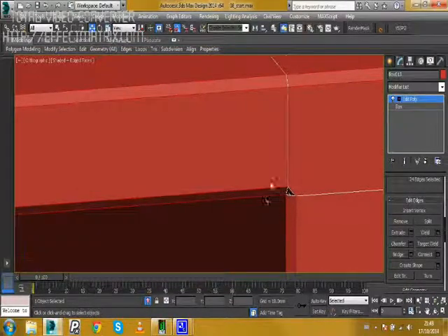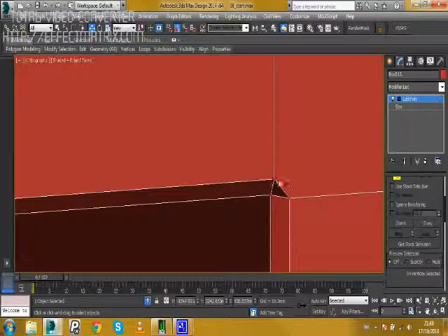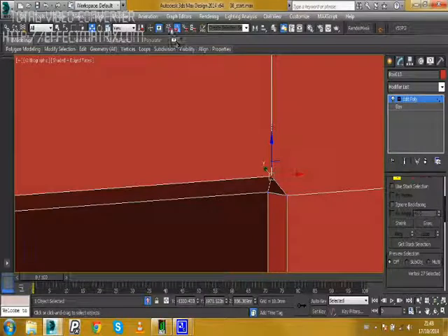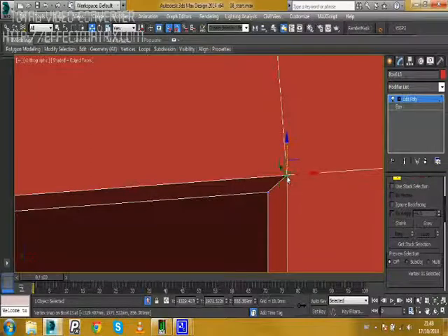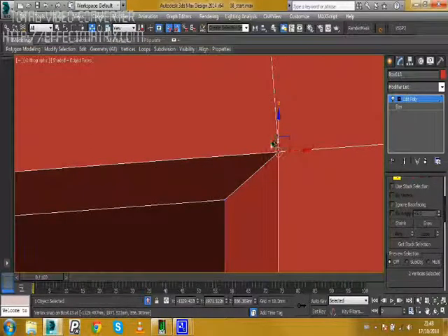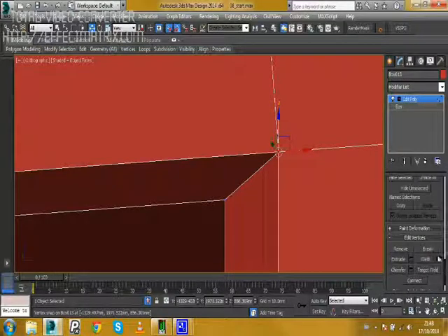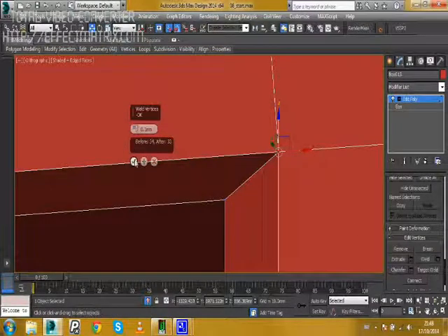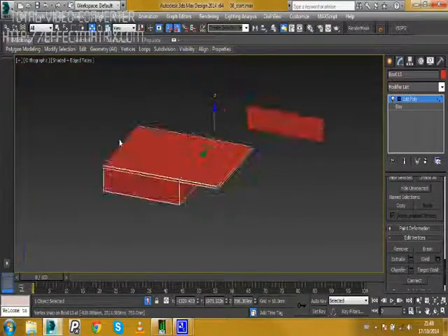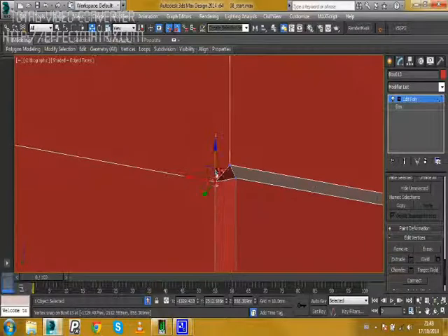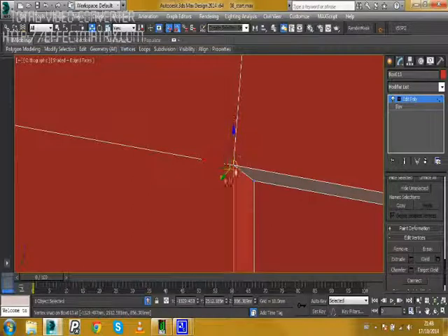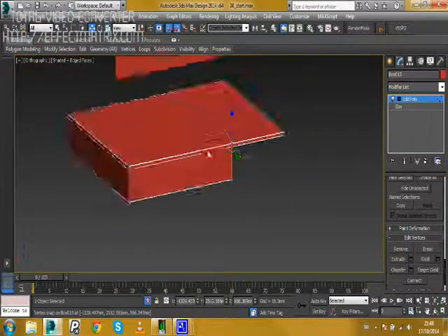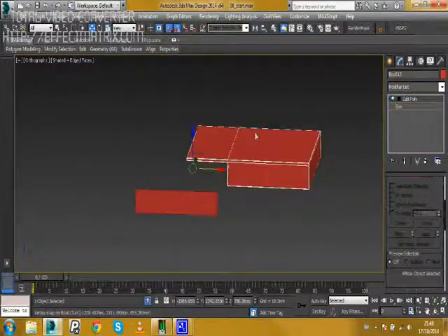You can see we've got some triangles here, so I'll show you how to remove these. If you go to your vertices, we'll just select this one, turn on your 3D snap, and snap it on the X axis to this point. We'll do the same with this point, on the Z axis to that point. If you highlight over these, there'll be two there, and we'll just weld these together. You can see it's removed one. OK that. I'll show you again round the other side. Just select this vertex here, snap it up to that one there, snap it back along, select the two of them, and weld. This ensures we're only working with quads. Deselect that.